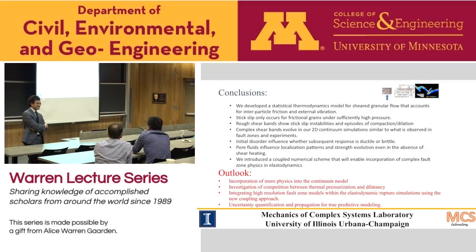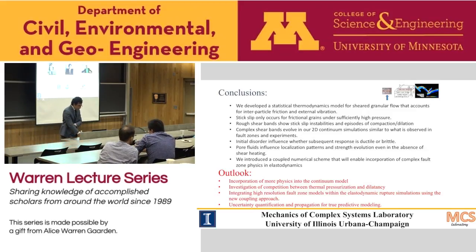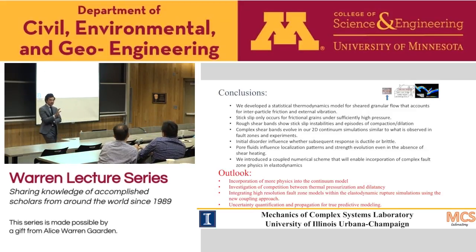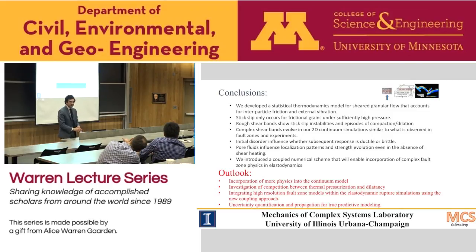I have a question regarding when you develop a continuum level model based on the discrete model. I guess you introduce a length scale in the continuum model. Right. What is this length scale and how do you determine it? Yeah, so actually, first, the STZ theory is a continuum model that homogenizes the discrete physics underlying the granular mechanics. The short answer is that this length scale is proportional to the grain size.